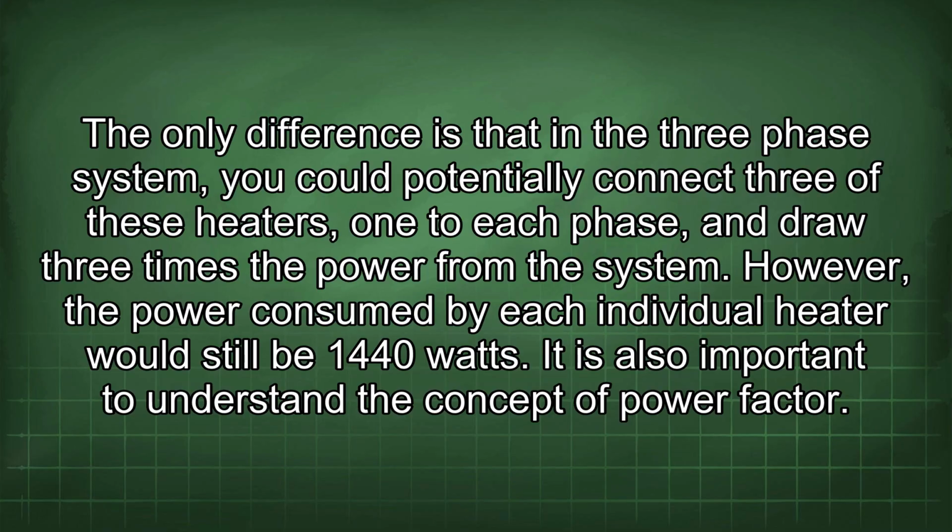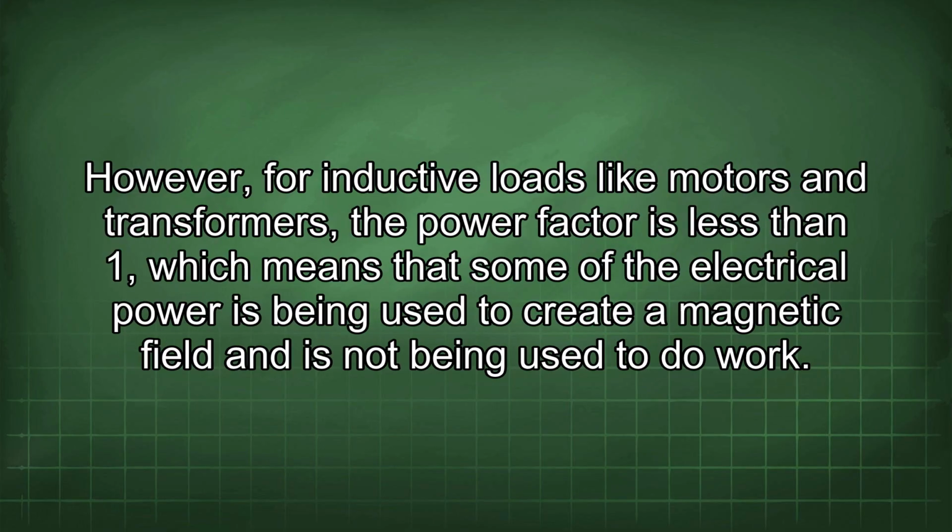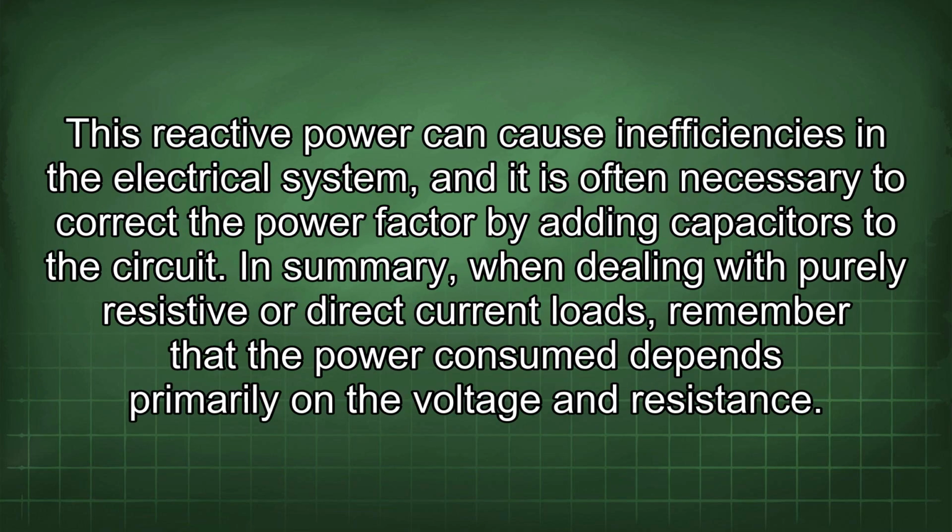It is also important to understand the concept of power factor. Power factor is a measure of how effectively electrical power is being used. For purely resistive loads, the power factor is 1, which means that all the electrical power being supplied is being used to do work. However, for inductive loads like motors and transformers, the power factor is less than 1, which means that some of the electrical power is being used to create a magnetic field and is not being used to do work. This reactive power can cause inefficiencies in the electrical system, and it is often necessary to correct the power factor by adding capacitors to the circuit.